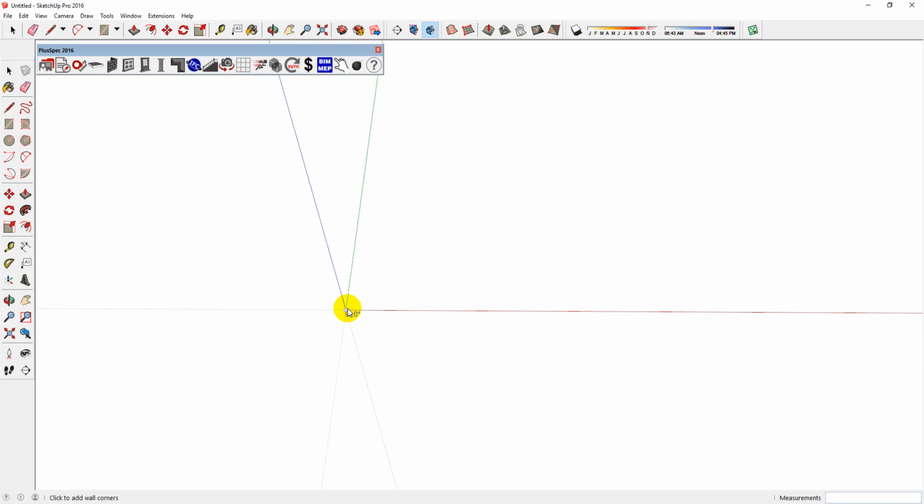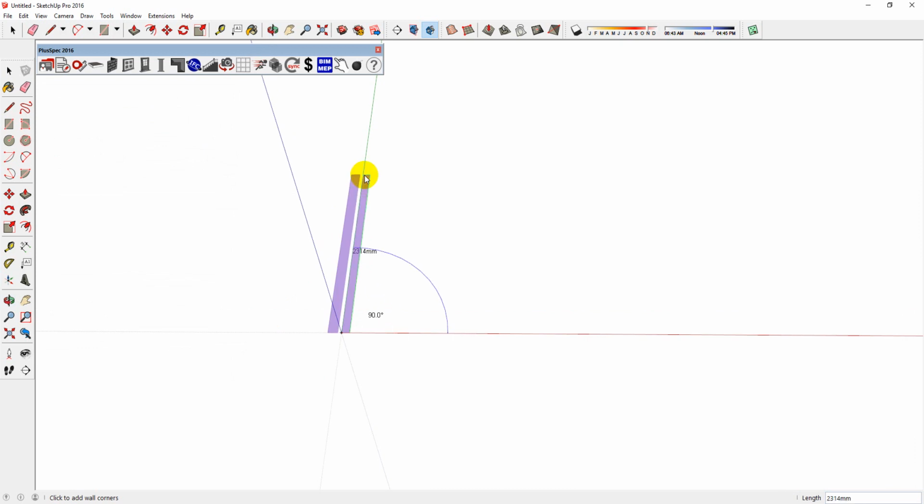Don't hold the button down, just tap it and let it go. And then drag it in a direction that you want to start drawing. With Plusspec, always try to draw clockwise, as this sets the exterior face to the outside of the wall.